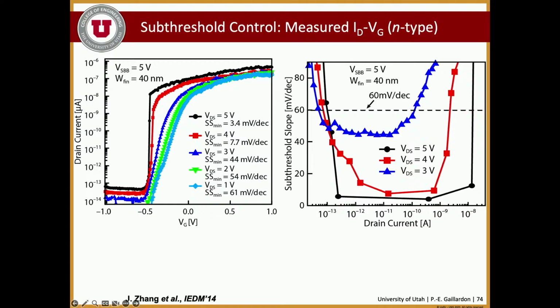But using this kind of principle, you can have devices that do switch very, very quickly. The community has been chasing these kind of devices for a while with the idea that if you can turn things on very quickly, we can reduce the VDD, right? Instead of having to stay right there when it's nicely turned on, you can reduce VDD there. And reducing the voltage, reducing the power consumption, right?